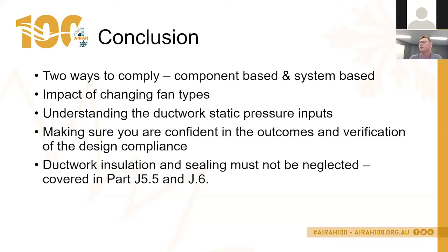So the full load operating point is the point at which the fan efficiency is calculated. So you do need to do your selections and find out the full load operating points of your fans when you do your selections, and then use that for the calculation of the efficiency.